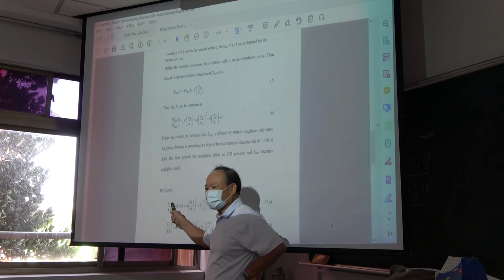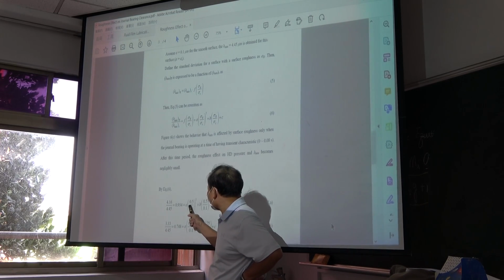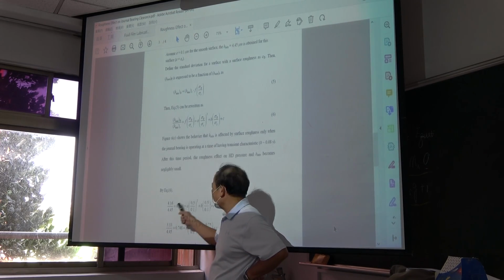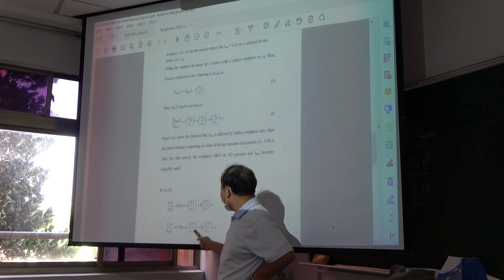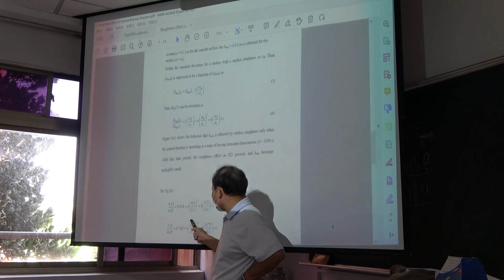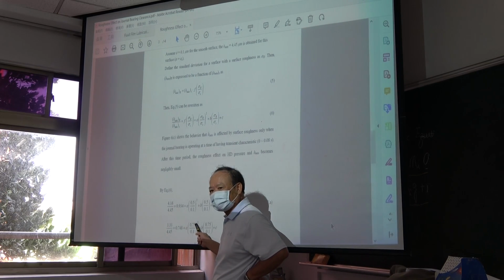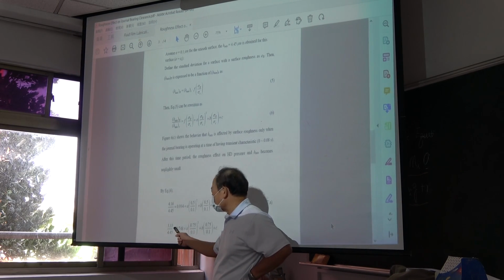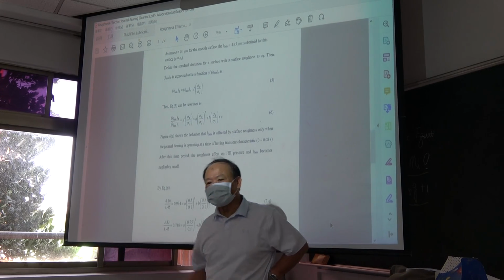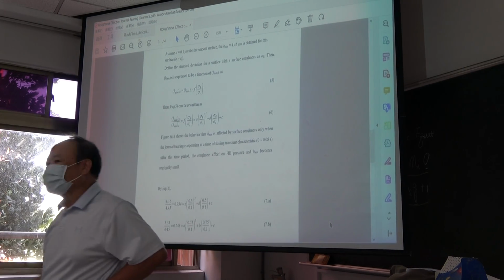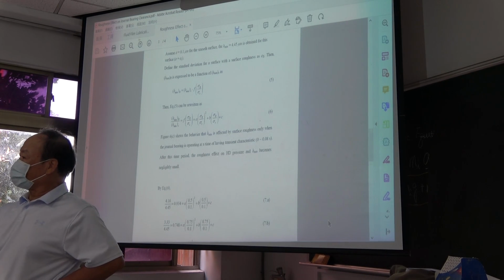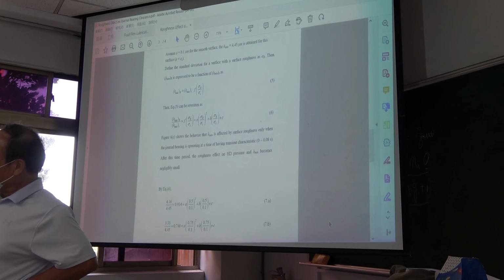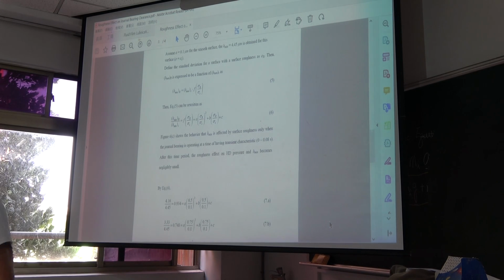This smooth roughness is this value, and then you have a minimum fin thickness of this value. Now you change your surface standard deviation to this value. Then your minimum fin thickness reduces. So write down: you increase your surface roughness, you will decrease your minimum fin thickness.